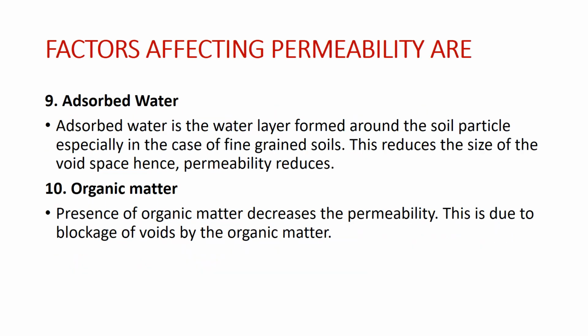Now, if we talk about adsorbed water, we have earlier discussed adsorbed water in one of the lectures. Adsorbed water is the water layer formed around the soil particles. So basically, this reduces the size of void space and permeability reduces. Organic matter also decreases permeability because it blocks the voids.